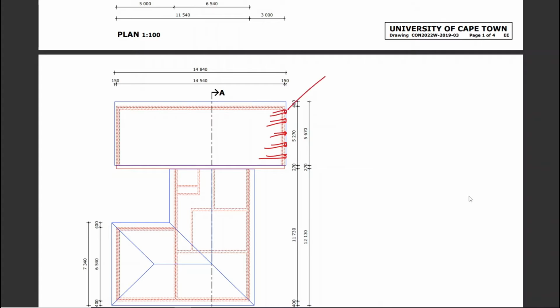That means you need to account for them under eaves and verges. And that little 150 overhang, you're going to apply your, well, actually not going to apply anything. I need to correct myself. It is taken as 150 straight. So these purlins are 150 over, and you're just going to have to multiply by the purlin perimeter. So let's say it's 2 times 38 and 2 by 50. And you're going to say, well, Anthony, that's a bit weird because I haven't been doing that. Well, we have been doing rafter ends on slope have a factor involved.